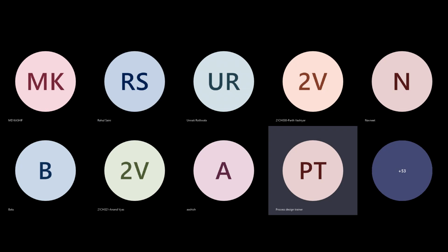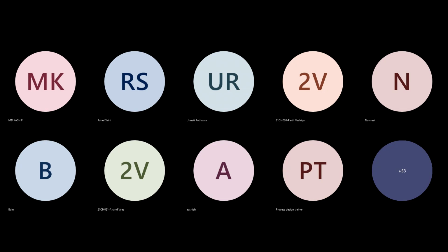You can also add a booster. Otherwise, I don't know exactly, but this PD pump will automatically suck. You can check the data sheet of the pump, what the suction is. Otherwise, most of the time, a PD pump always gets the fluid. Initially, it takes some amount of time, but once it gets it, it will pull the fluid on its own. There is no need of a booster, I think.